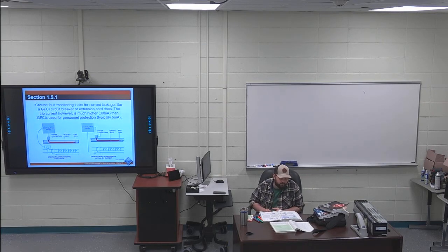Page 10, 152, continuity monitoring. The first sentence is highlighted with two. You'll have two questions come out of the first sentence of 152. Continuity monitor verifies that the voltage is present at the end of the termination. Key in on that. Voltage is present at the end of the termination of a heat tracing cable run.